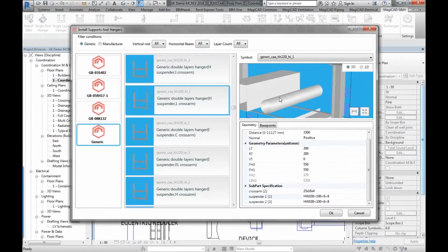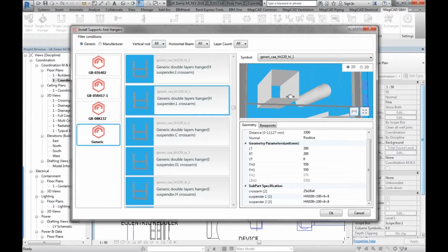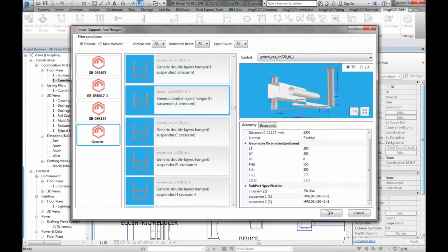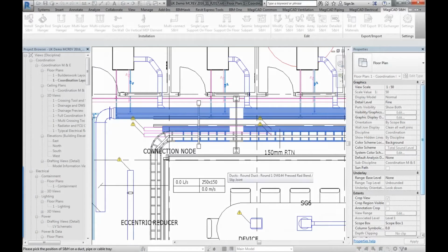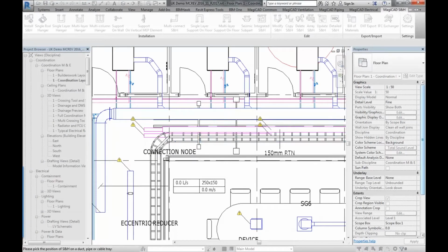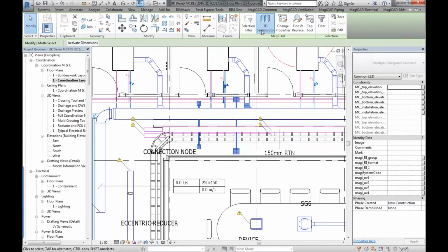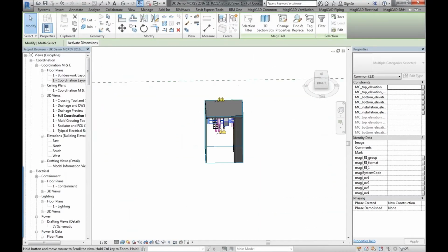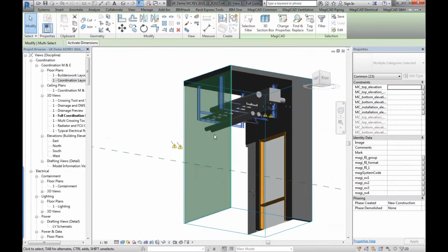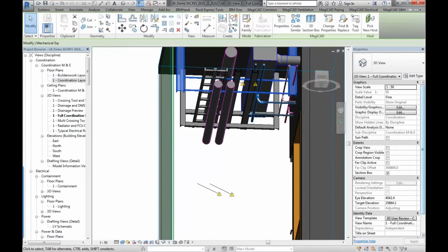And then once you're happy with the dimensions, if you want to select the specification of the steelwork, you can choose from UK steelwork data, and that's the cross arm. You can see there it's quite a narrow one for this ductwork. And then this suspender rod, depending on the type of object you've chosen, in this case mine is like an I-beam, so that specification is related to that I-beam. You can see if you choose a different I-beam, then obviously the spec will change.